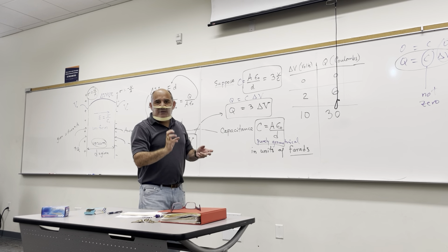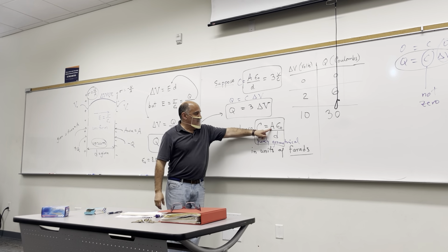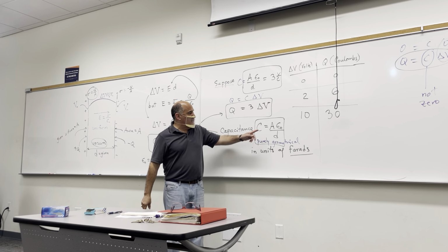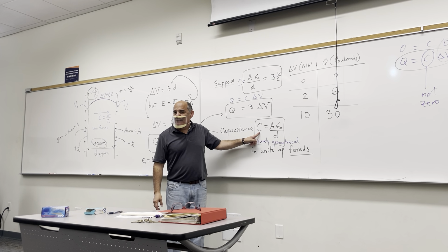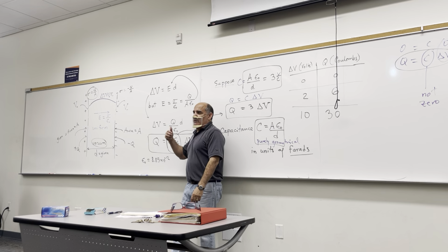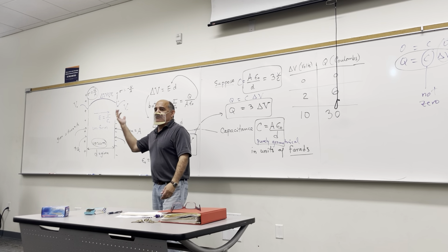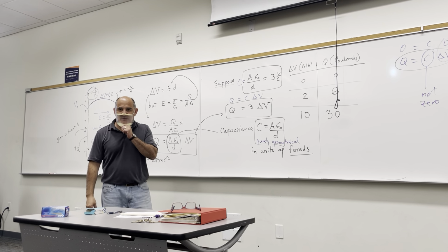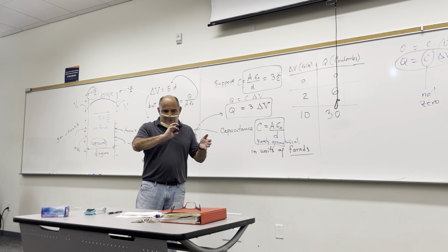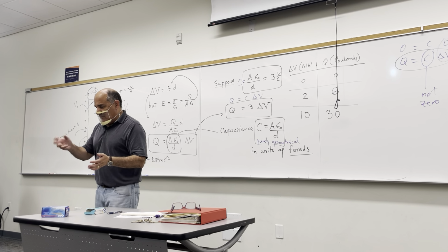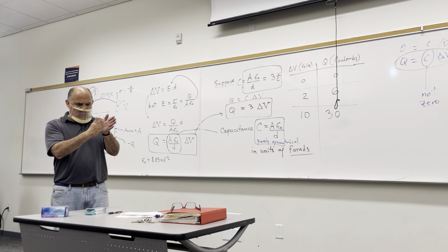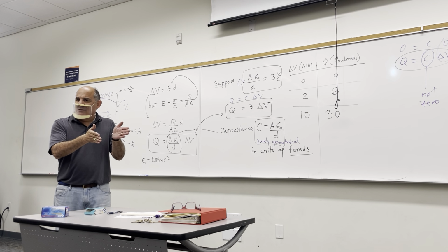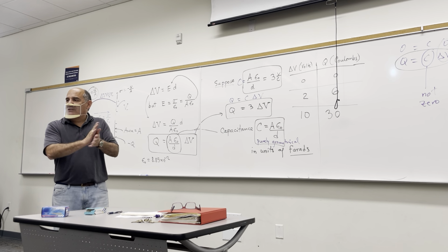So you're changing the effective area between the two plates, and you're changing the capacitance. By changing the capacitance, you can tune into another frequency of electromagnetic wave coming in. You're physically turning one plate; the other one stays fixed, so you're changing the area between them.